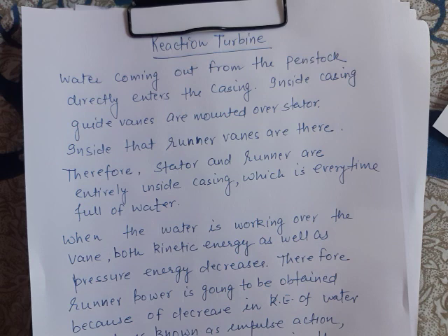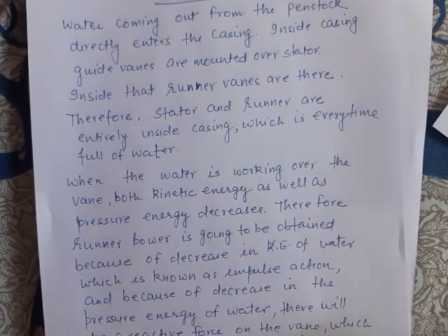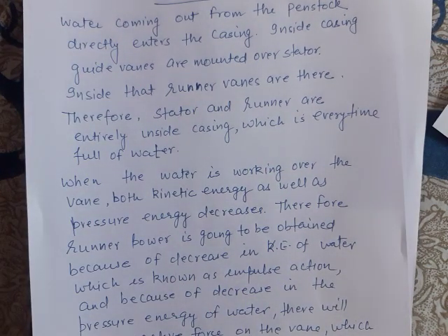This casing is full of water at each and every moment, and the stator and runner are mounted inside the casing itself. Stator has a set of stationary blades which are known as guide vanes, while the runner has a set of moving vanes to obtain the runner power.